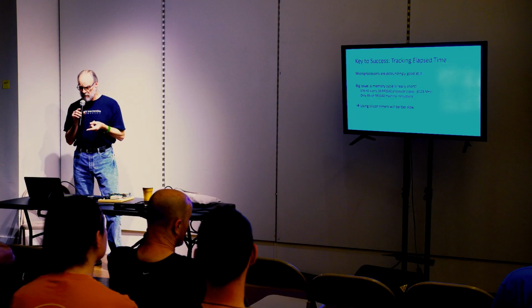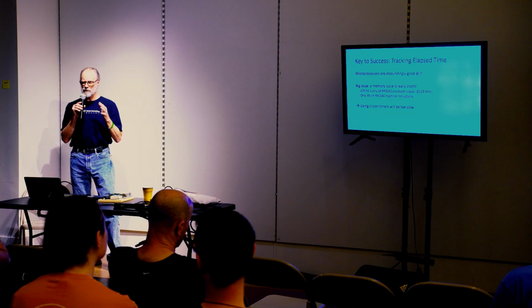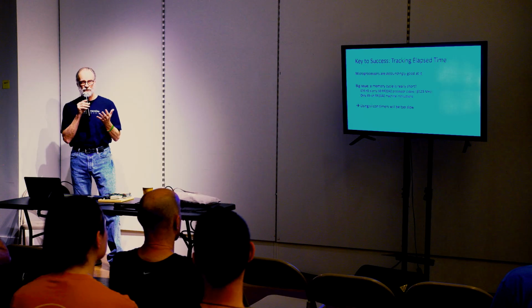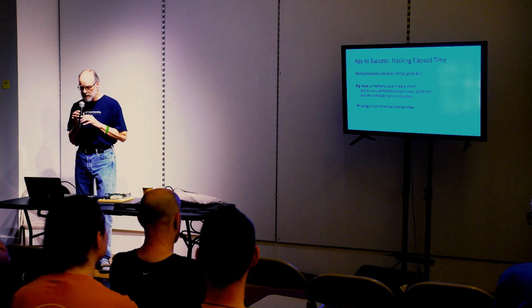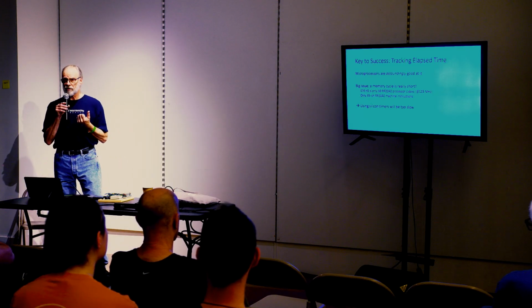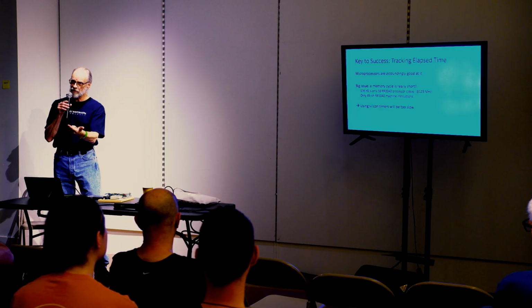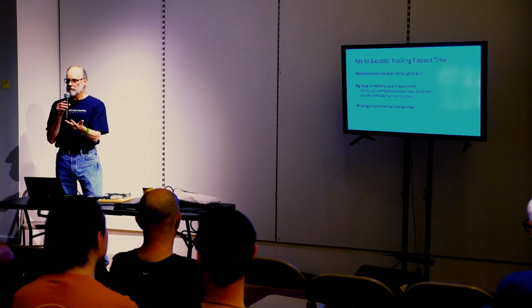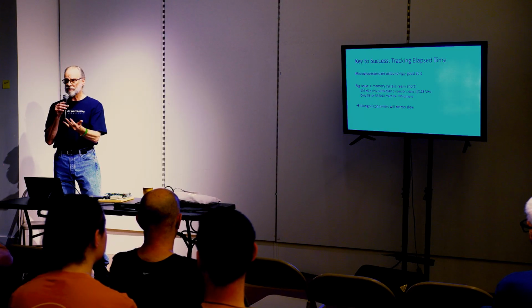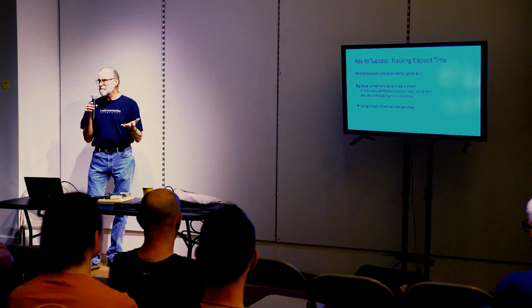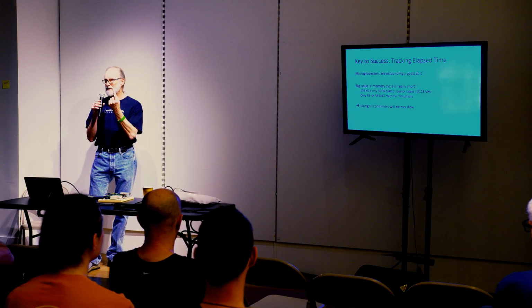So it came out to about 59 processor clocks is all I'd get, and that means that it would be about 45 or so instructions. That's all I get to do. And using silicon timers is way too slow. By the time you read a timer, subtract off a time zero, compare it to a value and branch, you've already spent 4, 5, 6 instructions, and all you've done is established one point in time.